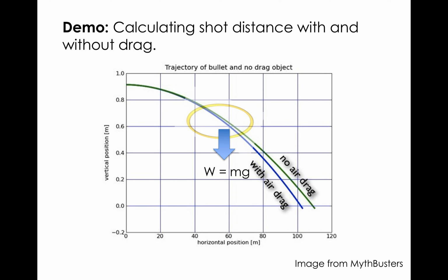What is happening in actuality is that there is also a drag force, FD, that is acting on the rubber band tangent to its velocity. Okay, so it's acting in the direction of the velocity. So here it would be pointing back up along this curve. So it would be acting upwards and to the left, okay? That drag force is computed experimentally, so there's an equation for it. Okay, so that force of drag is equal to 1/2 c rho A V squared. C is called a drag constant, drag coefficient.